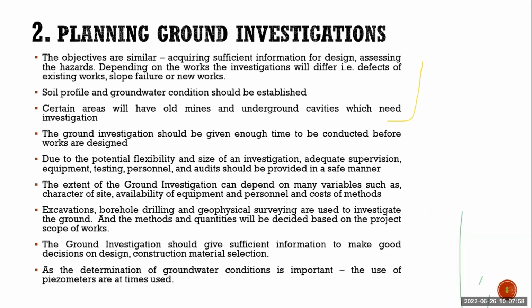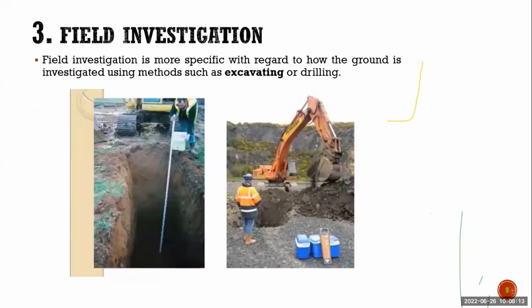And also, if we need to know about the groundwater condition details, or if we need to monitor in future, that details also will be included in the scope. Okay, that is called planning for the ground investigation. Now, once planning is over, like I mentioned in the very beginning slide, in the first slide, these details will be sent to the geotechnical contractors, and they will quote, and once the quote is approved, then they will come and perform the field investigation.